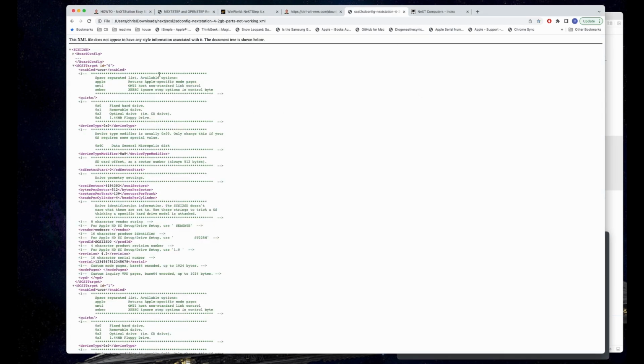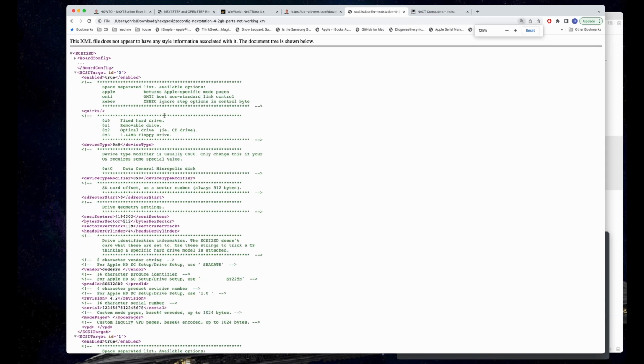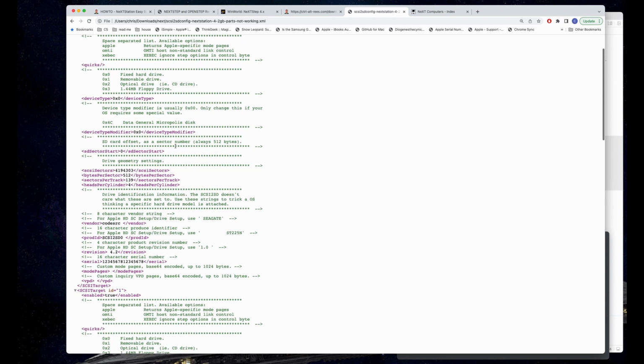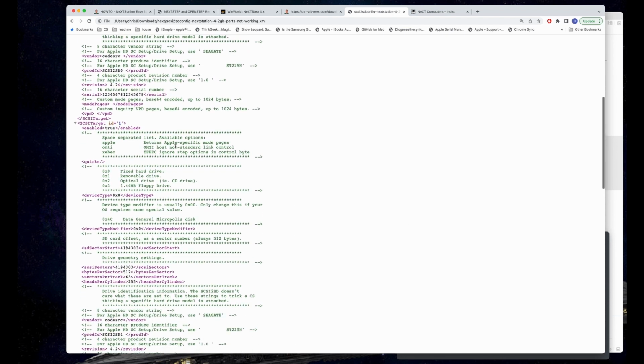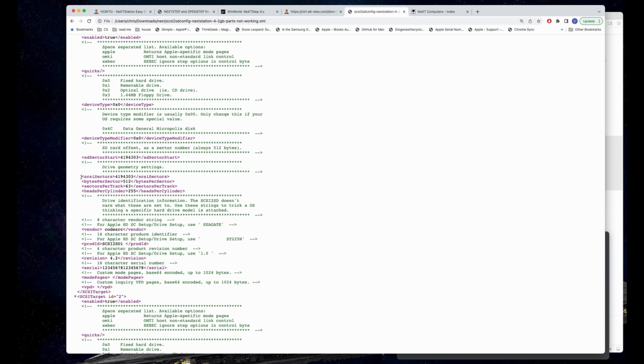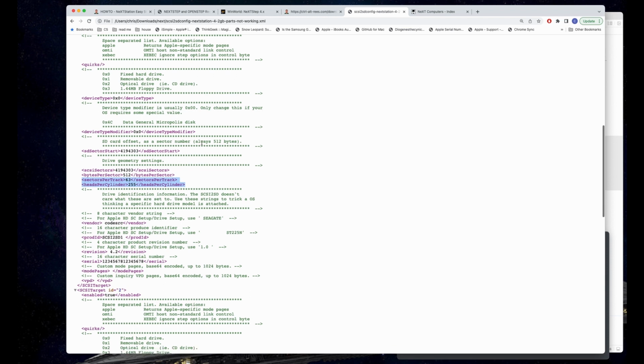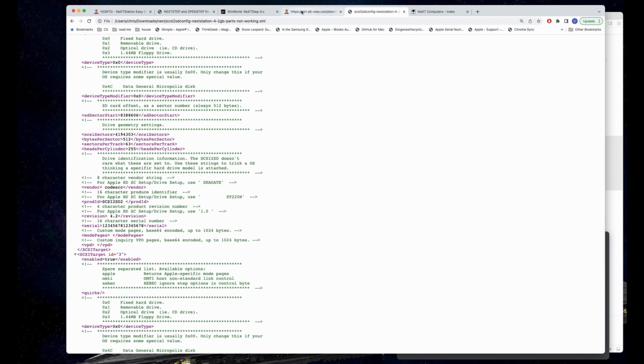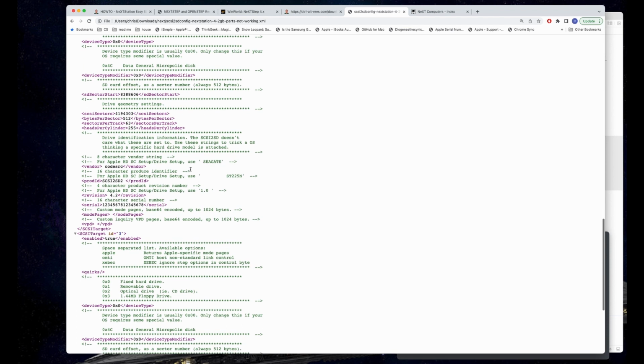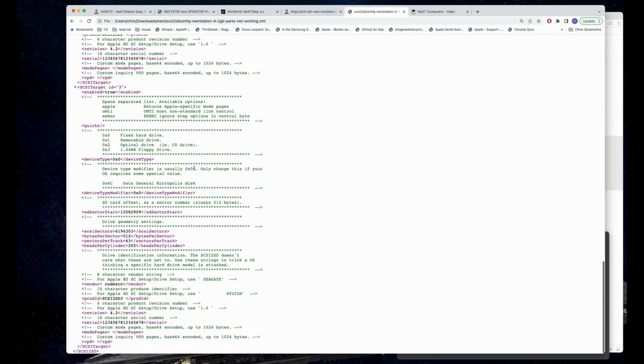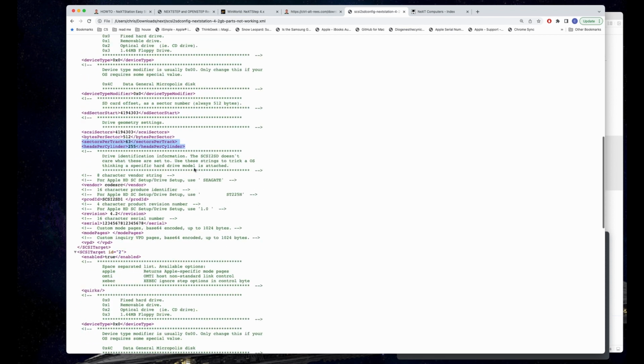So this is the configuration, what that looks like under the hood, and the settings that you want to look at are these ones here. Now, if you just enable another SCSI device, they will set, I believe, these two values that the NeXTstation will not like. So you have to essentially copy that from the first one that will set up correctly and just paste them into any further device that you decide to add and activate on the SCSI 2SD device. So look out for those.